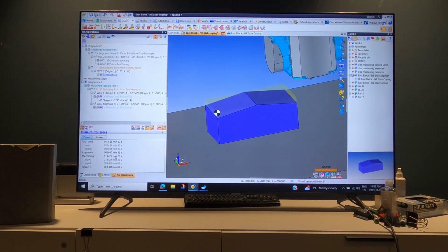Set your tool, set the speed and go. You don't have to set any parameters. Even if the shape is really complicated, it's all there. Same thing, you're just roughing. Roughing is the easiest part of the calculation. That's why I tell you that very often, maybe just the roughing is enough to give to the stone mason to finish manually. So maybe we can have a look on the machine now if it's correct, and then we will do another exercise.